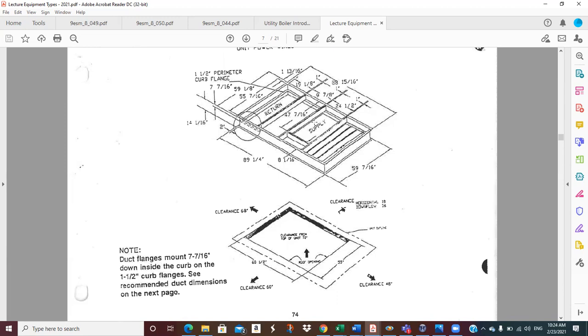Okay. Now these roof curbs come in different heights, and some are called noise cancellation or vibration isolation, I guess. Because think about this. You're setting this on the top of the building. Let's say it's a big 3-story, 4-story bank building. Well, the president of the bank's office is usually on the top floor with the big windows looking out with the best view. Now, if you put this HVAC unit on top of the president's office and it makes a lot of noise, you're going to be in trouble. He's going to complain, or his secretary's going to complain, and it's going to go back through the architect or the contractor, and it's going to come back to your lap. This daggone thing is too loud, do something about it. So you better consider that when you place the unit.